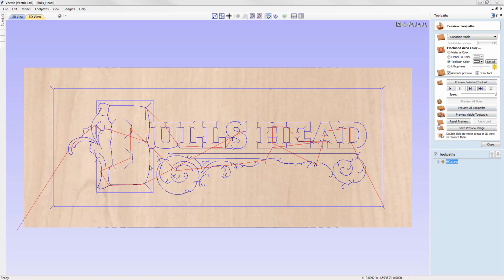And so this toolpath has been drawn for us in the 3D view, and this literally represents the coordinates that the software is going to tell the tool to move to in order to carve the sign out. And this is very useful for me to see the actual paths here, but it's more useful for me to visualize the actual cutout simulation, and that's what this preview function is for.